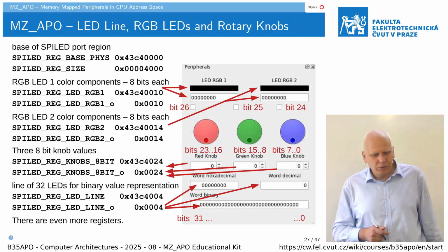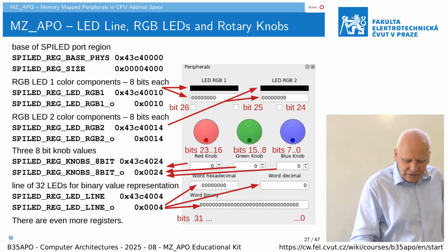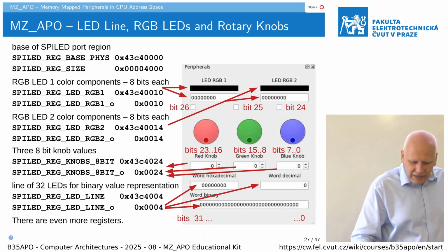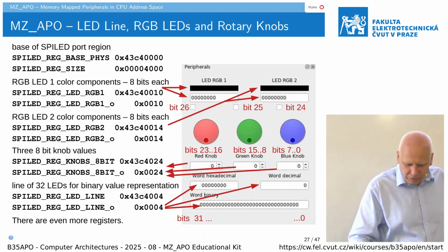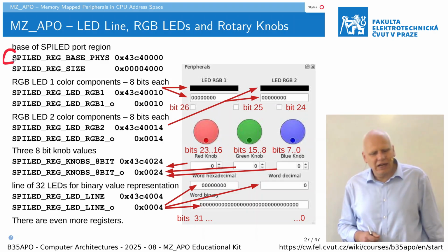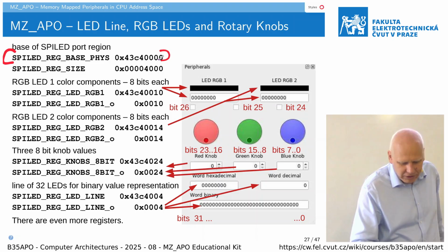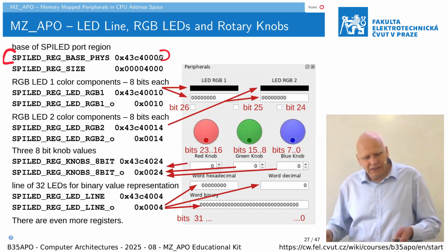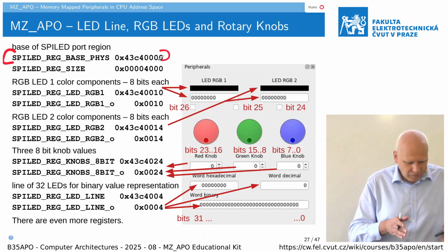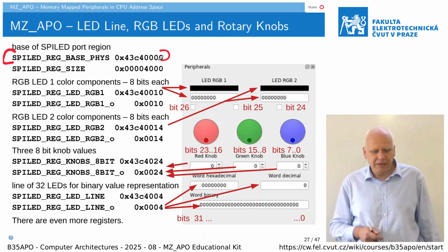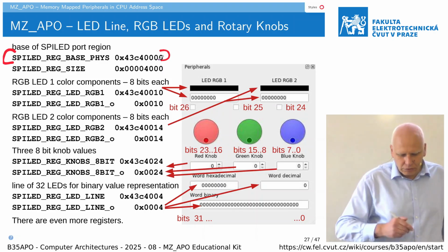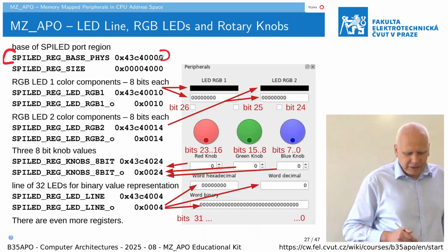And now what you can do, again exactly the same on the simulator, is access this block of the peripherals. The only difference between the simulator and this hardware is a different base address, because there the base address is given by the window where we can map the peripherals in the FPGA, in the programmable logic, to the physical address space of the processor.